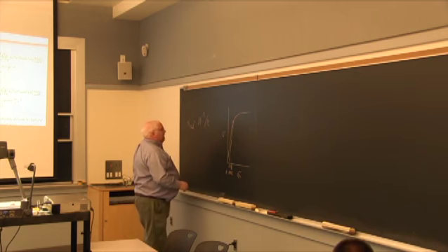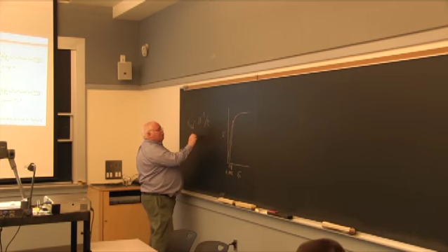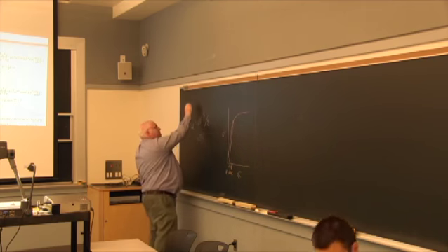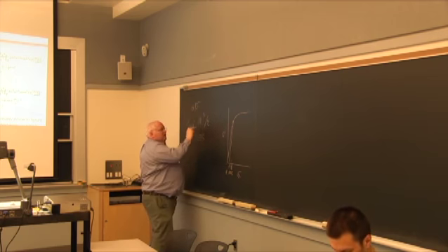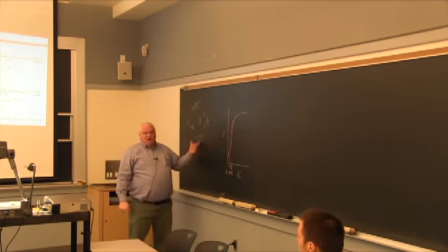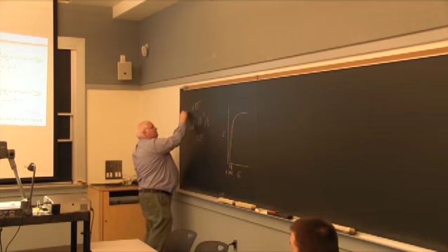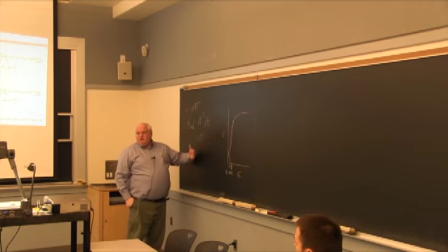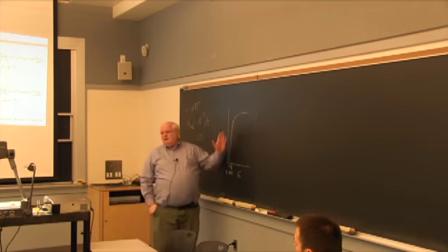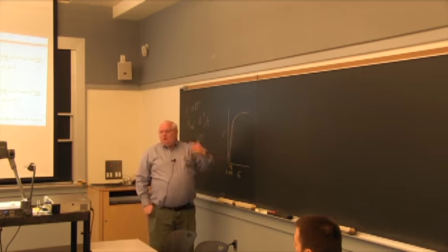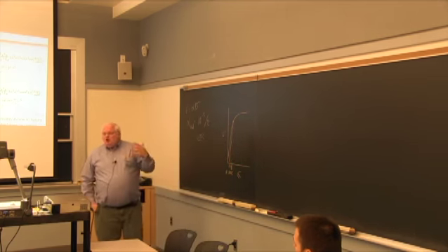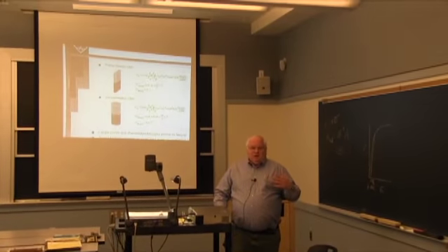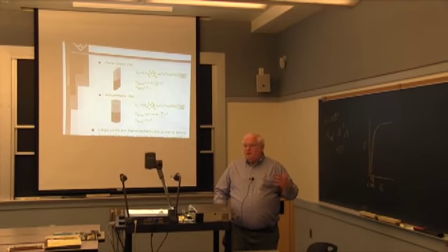Well, that means that 200 degrees centigrade should, so if it's alpha delta T, to give you this much strain, 0.002 strain, if 0.002 strain is the strain at yield, 200 degrees centigrade, and if you want to say, okay, let's take the fact that this is a secant, and you take the secant modulus and everything, 0.003. So I usually say 200 to 300 degrees temperature differential is going to cause yield level residual stresses, approximately.